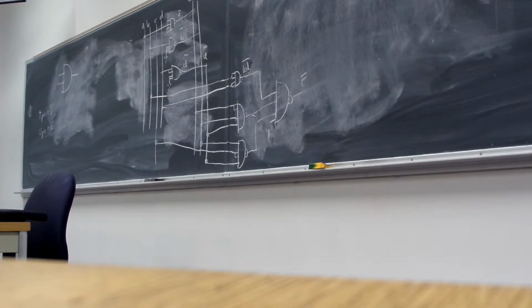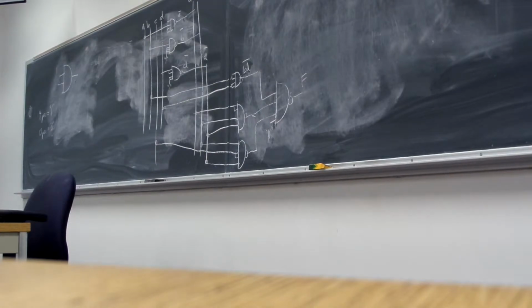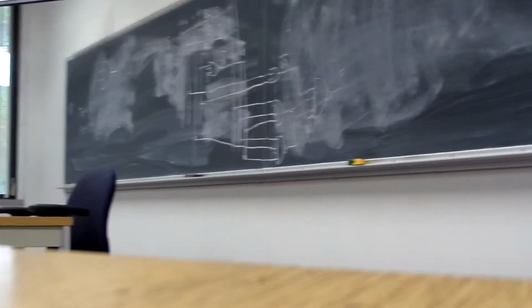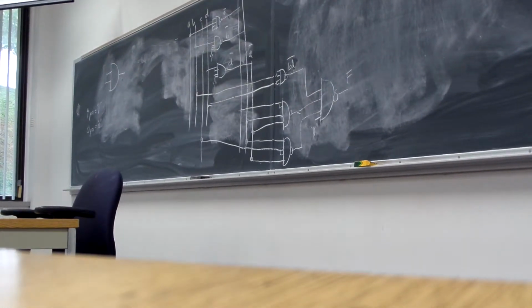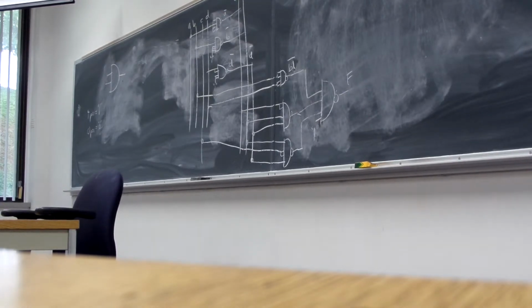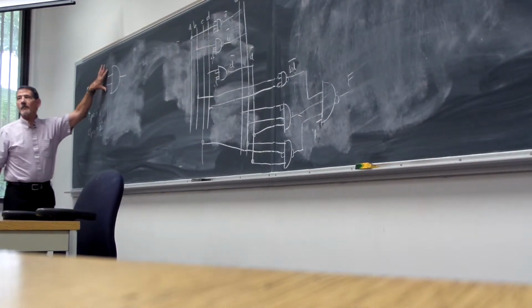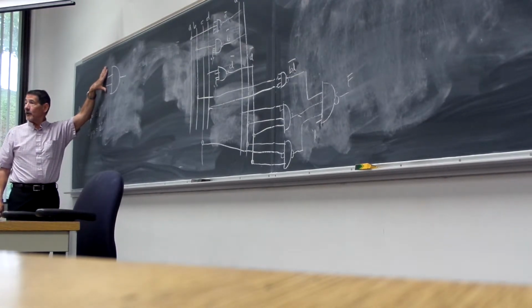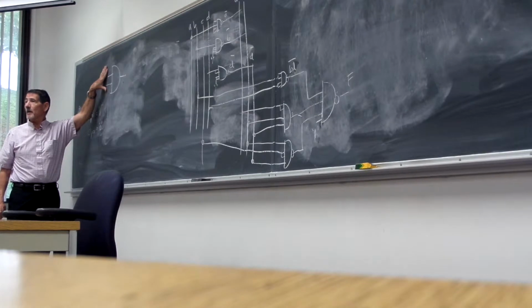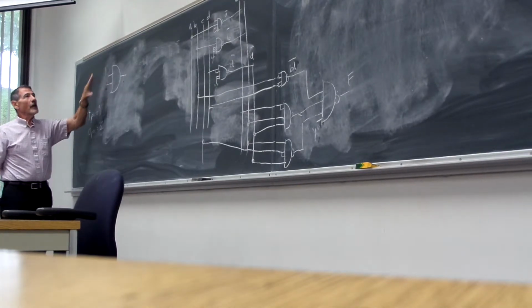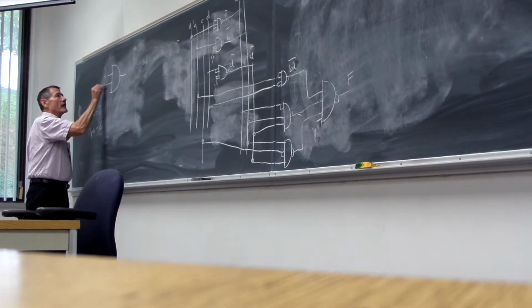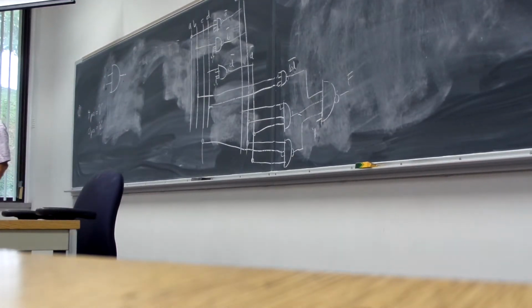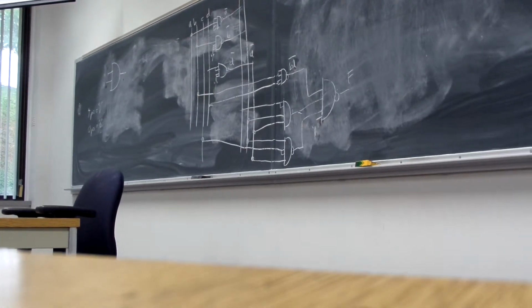So whenever you hook two systems up, you have to pay attention. I went over this time and time again in 402, right? You have to always take into account loading and how, when you interface things, they interact. Okay. So if we had a pressure system here, you would have to be concerned about what kind of flow would be associated with that? In an ideal world, if I said that I'm going to put 4 PSI there, how much flow would you like to have coming out of whatever's driving this gate?